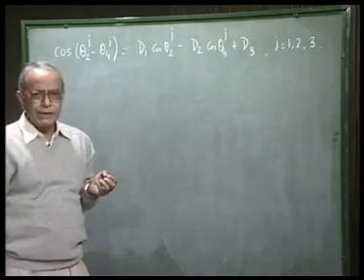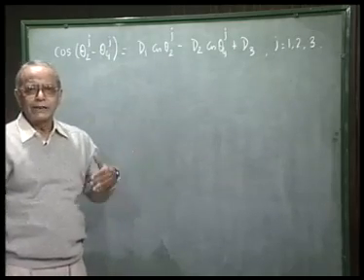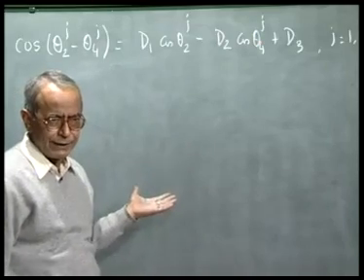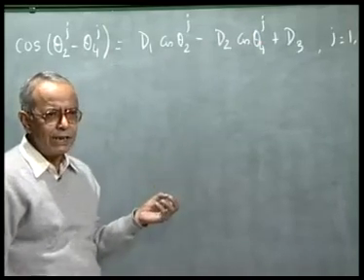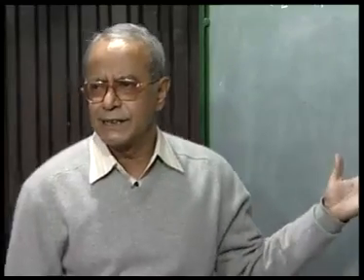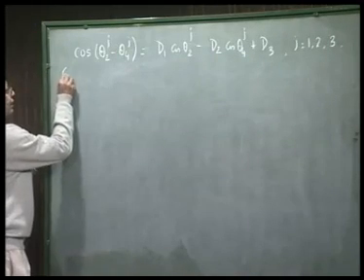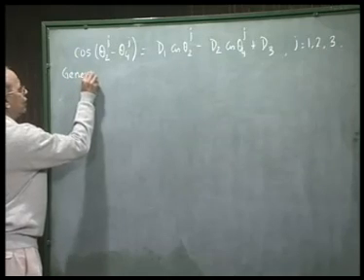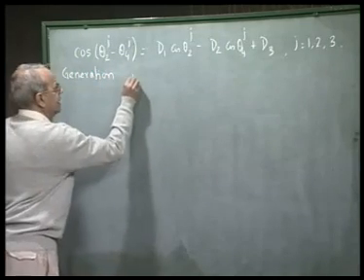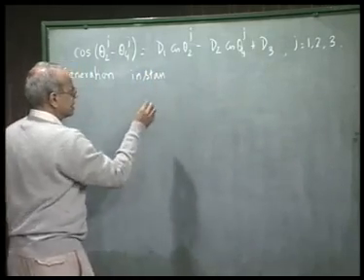It may be pointed out it is the link length ratios that matter, because if the whole figure is scaled up, we get the same relative movement between various links. That is, the linkage remains the same, it is only the scale of the drawing. So, L1 I can choose arbitrarily or conveniently, and then we can get the other 3 link lengths L2, L3, and L4. This equation can also be used for generation of instantaneous kinematic relationship, not just position but velocity and acceleration as well.